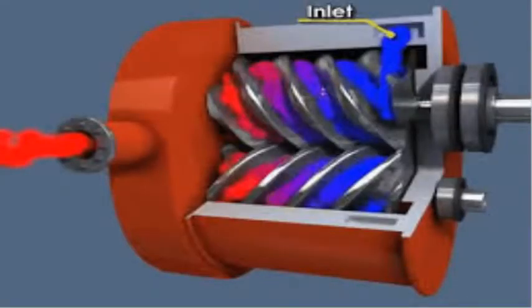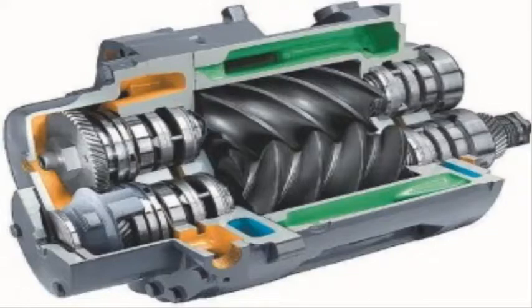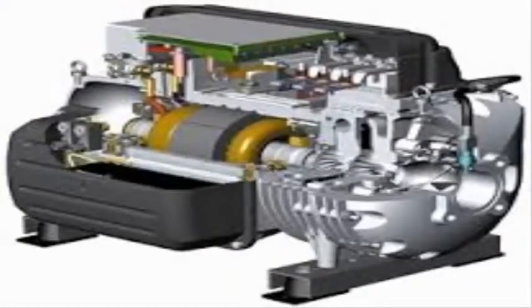Screw compressor. The screw compressor uses a pair of helical rotors, where it traps and compresses the gas as the rotors revolve in the cylinder. In HVAC, they are usually used in systems with 20-ton capacity and above. The male rotor and the female rotor are built inside the cylinder. The low-pressure refrigerant enters one end of the compressor and the resultant high-pressure refrigerant is discharged into the opposite end of the condenser. Screw chillers are available in capacities ranging from 20 to 1000 tons and even higher from a few manufacturers.